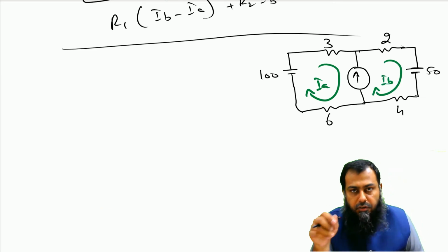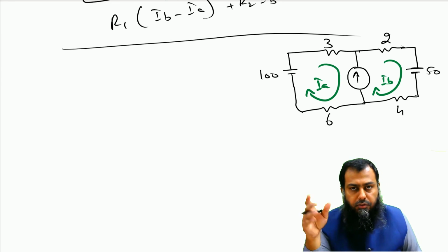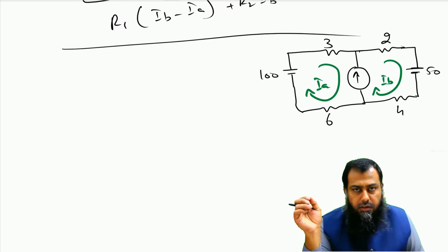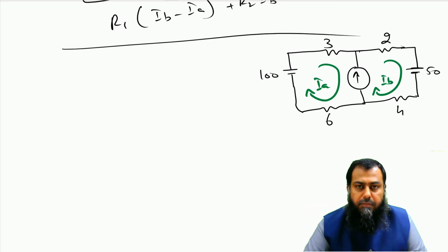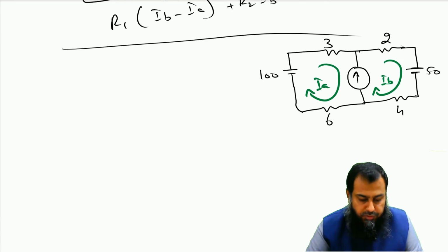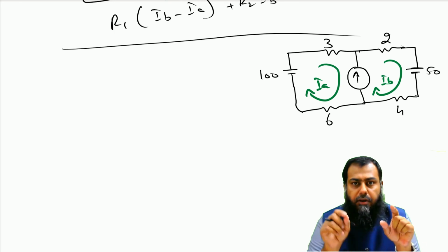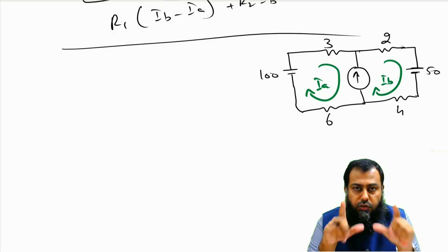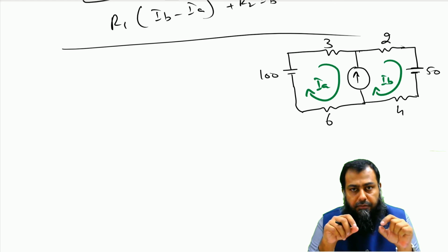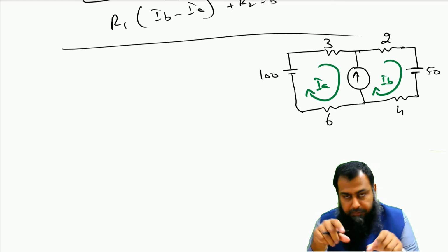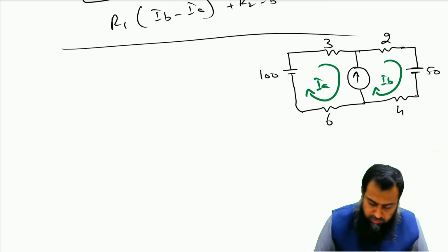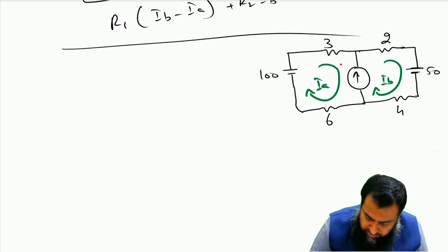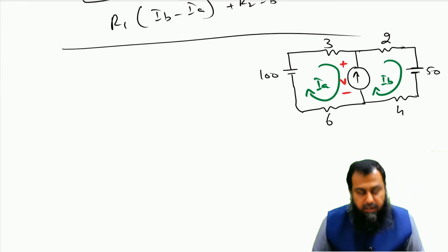Let us first solve it through the conventional method. What if we do not go for some other technique? So how can we actually solve this given circuit? Now, similar to the node voltage method, where we actually assume some current flowing through that voltage source which is common between the two nodes, in this particular mesh current analysis method, we shall assume some voltage which is available over the particular current source, right? That is very important. So now let us assume that we have some voltage here, and that voltage has this polarity.